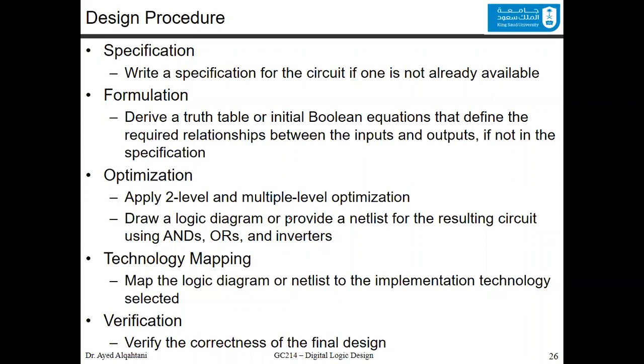And remember, we have standard forms like the POS or the SOP. The technology mapping maps the logic diagram or the resulting netlist to the implementation technology that was selected. And the verification: when you're done with your design, you verify the correctness of this final design.